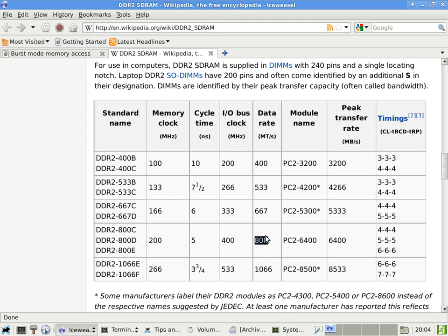The routing, to actually draw a line from one point to another point without two lines actually crossing is hard. That's not easy to do. And when you have a lot of these lines going across like that, it becomes very difficult to design a board that can operate at high speed. So that's why they went from parallel back to serial, to make board layout easier, because with fewer lines to route, it is easier to design motherboards.